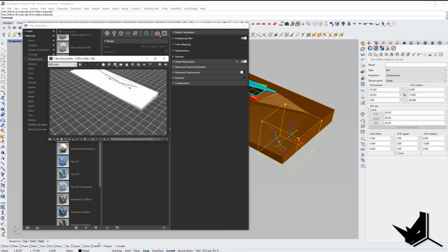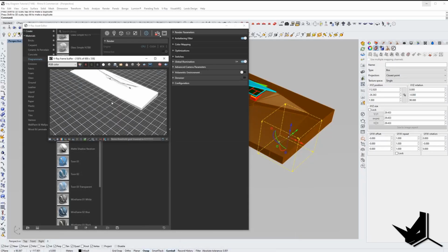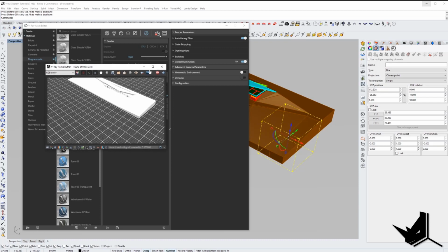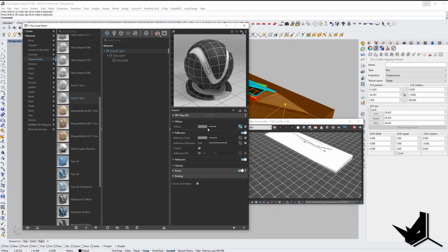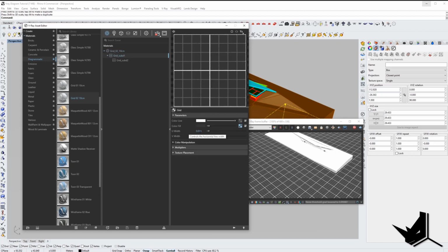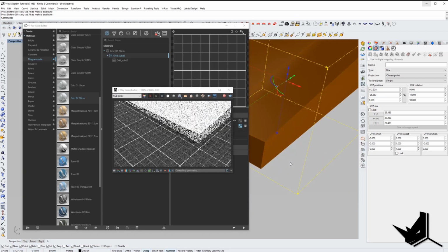I may think that the lines are a little bit too thick. So if you want to make the lines a little bit thinner, let's go to our material and adjust the initial width from 0.015. Let's put it to 0 to make them even tinier. And now I think that's fine. Let me just zoom in a little bit. Okay, so you can see how we got that grid nice.